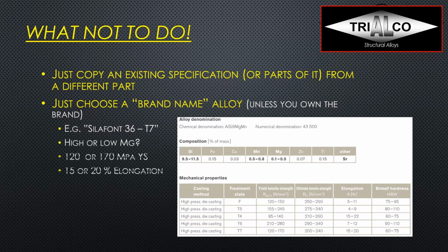So all these things, you really want to specify what you want as the OEM or casting buyer. You, as I said before, specify your properties that you expect, and then as the casting producer, then rather specify the chemistry and narrow down, in this case, for example, the magnesium content that will give you the properties that the casting buyer is expecting from you. So otherwise, you will just risk that you might have only one single source at a very high price.